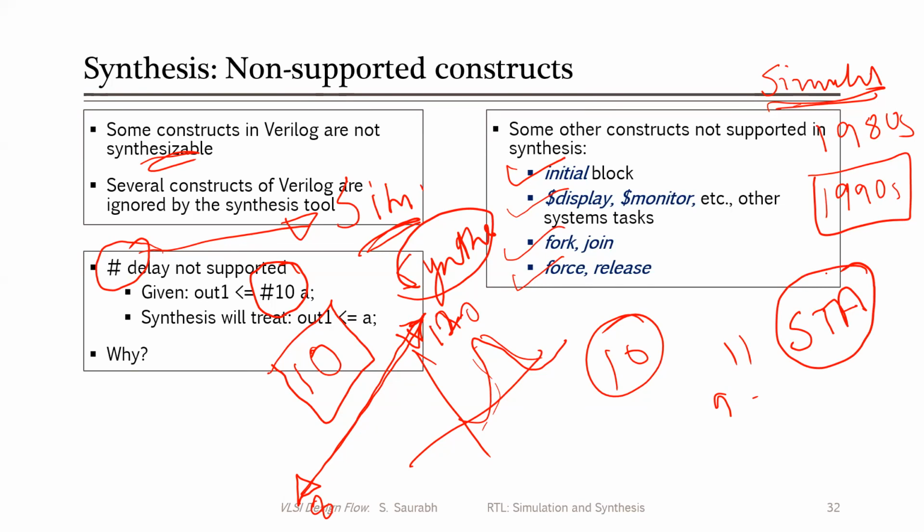To ensure that our design will say that the average value will be 10, but it will vary between 8 to 12 with this probability and so on, right? And that is what we design our circuit with, and this is easy to meet. And this is an important concept of this design flow, that we design for a given range with some margin, and that margin should be reasonable. It shouldn't be very wide or too narrow, right? And that is an engineering decision that we need to make.